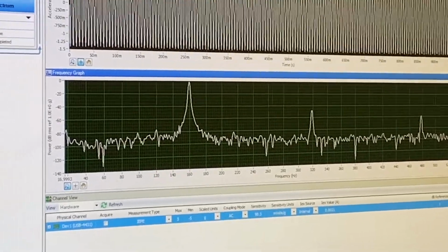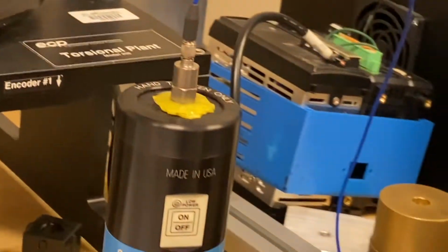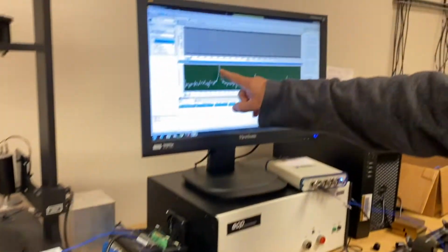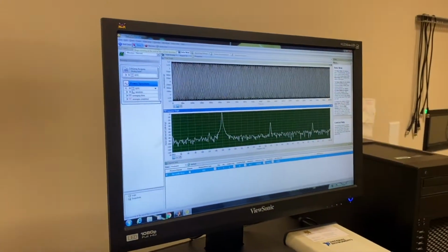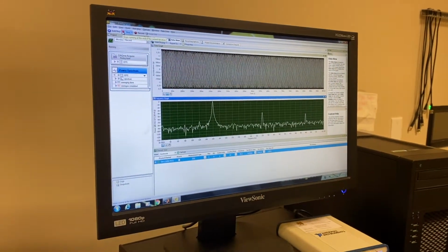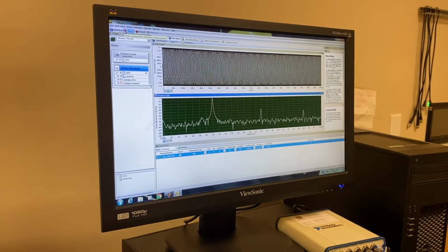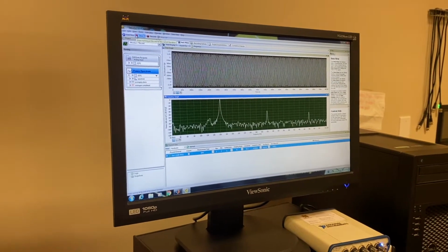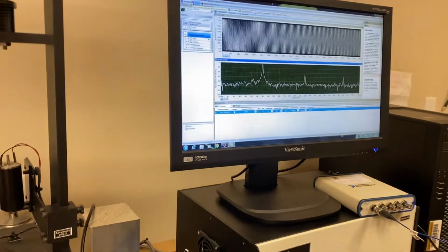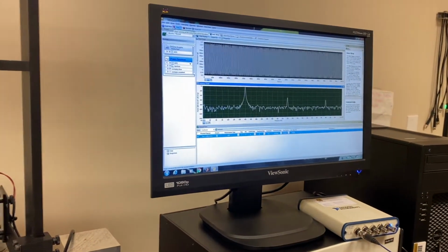If you run this and run this again, if you see this peak is telling me that the shaker is moving, or the signal is vibrating at 159.2 Hertz. This is our whole experiment. Our accelerometer is working nicely right now.